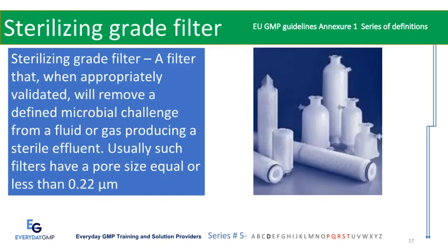Sterilizing grade filter: a filter that, when appropriately validated, will remove a defined microbial challenge from a fluid or gas producing a sterile effluent. Usually, such filters have a pore size equal to or less than 0.22 micrometers.